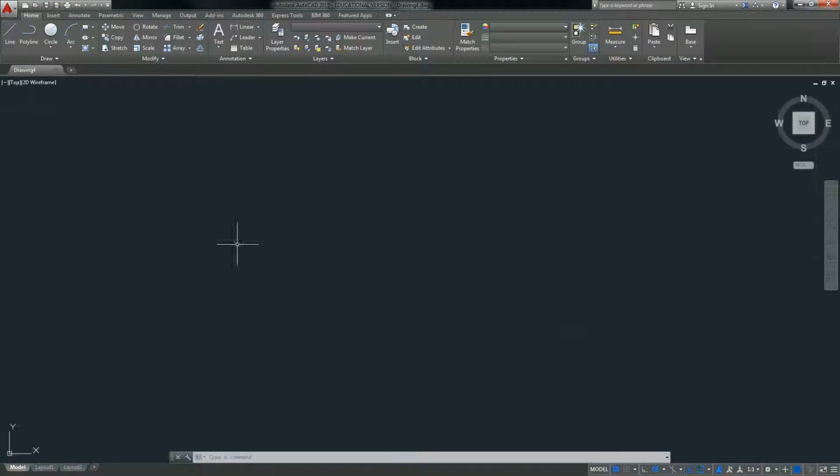ISO.dwt. And here I can see that I've just got a plain AutoCAD window. It's not in any 3D mode. It doesn't look orbited. There's no shade modes going on. It's just a plain view. And I can see that right now I'm on the top view. So I want to do this from the right side view, so I'm going to click this button and then click this button so that I'm looking at the right.